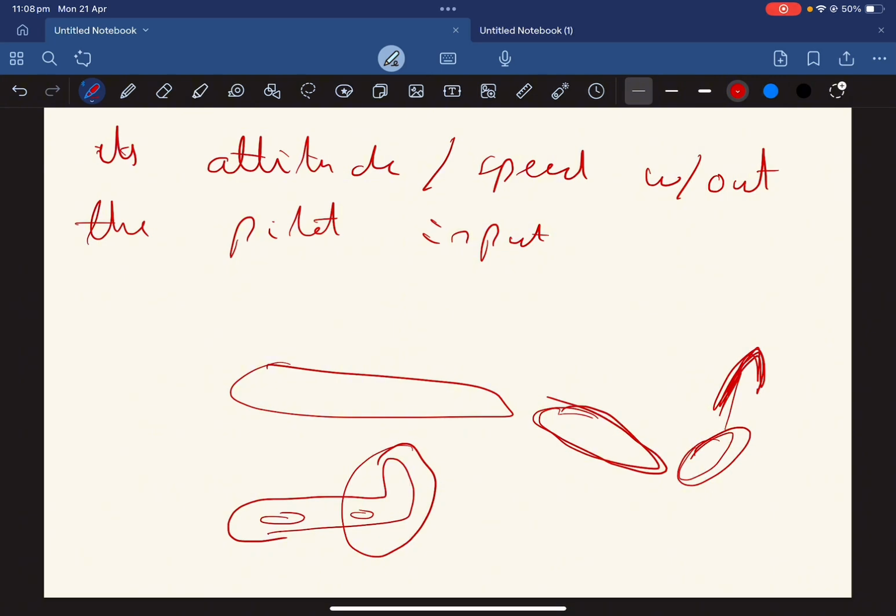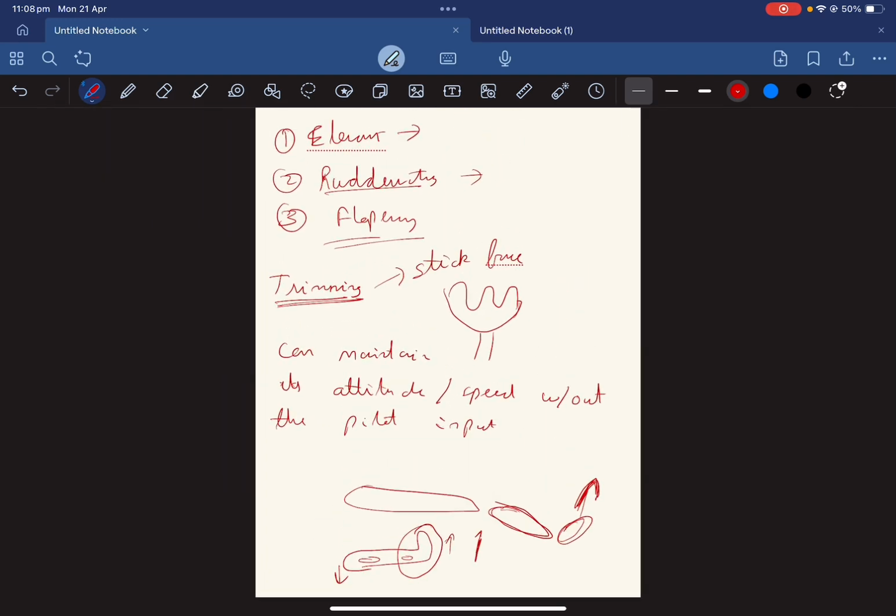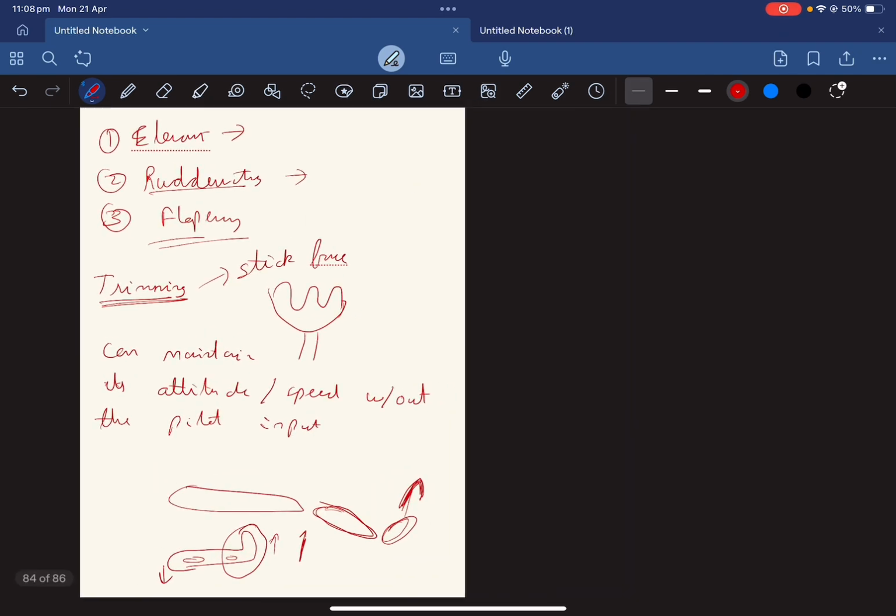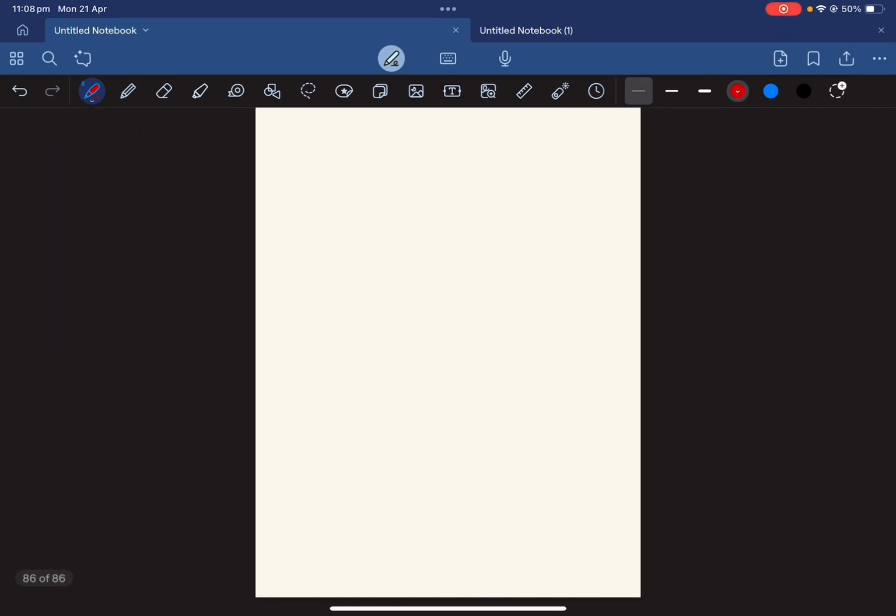Let's imagine, because when you're flying, it's hard to remember, right? So let's say this is a trim tab. If I move it up, it means the back, the elevator surface, is going to move down. So basically you're doing nose down trim. It's easier to remember when you're flying. This is something I've learned from my instructors. Just sharing info.